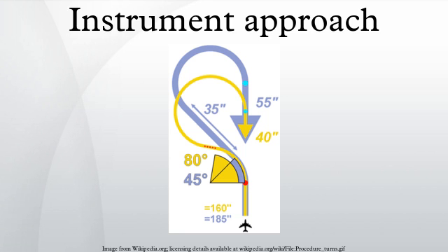If a runway has both precision and non-precision approaches defined, the MDA of the non-precision approach is almost always greater than the DH/DA of the precision approach. Because of the lack of vertical guidance on the non-precision approach, the actual difference depends on the accuracy of the navaid upon which the approach is based, with ADF approaches and SRAs tending to have the highest MDAs.